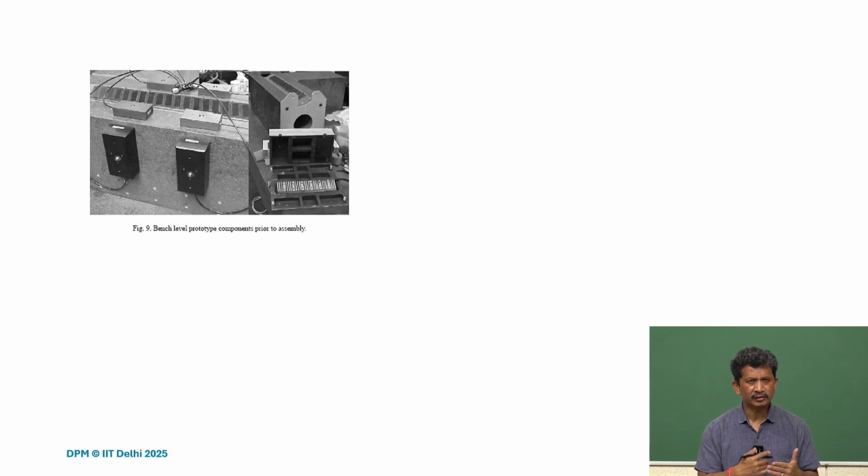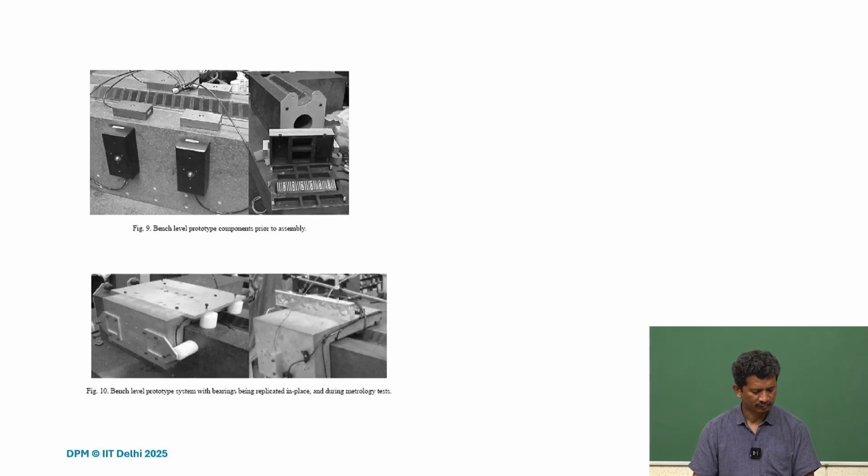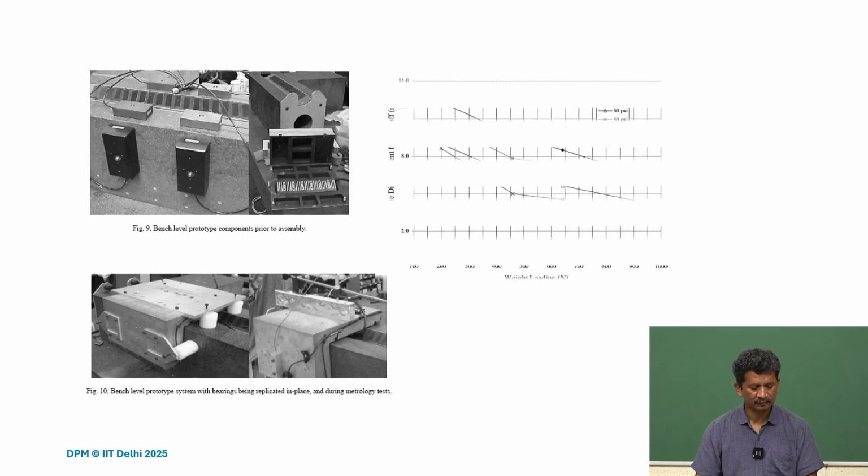So what are the various steps when it has to be fixed, or suppose you are using epoxies to embed things on the structure itself, what are the various steps. Each and every step is mentioned there. You can see first the air pads, and then you put the epoxy and let it cure so that the orientation of the pads is properly placed.